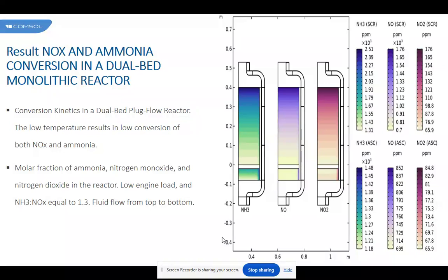In the simulation, we use a detailed computational model at the reactor scale which considers entrance length, turbulence dissipation, and internal diffusion limitations. To investigate the impact of using a dual cell substrate on conversion efficiency, pressure drop, and fluid distribution, the substrate is divided into two concentric regions. One is at its core and one at its periphery, and a different cell density is given to each part.